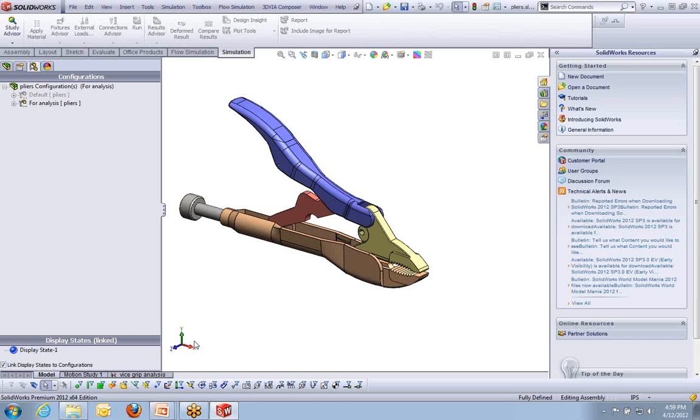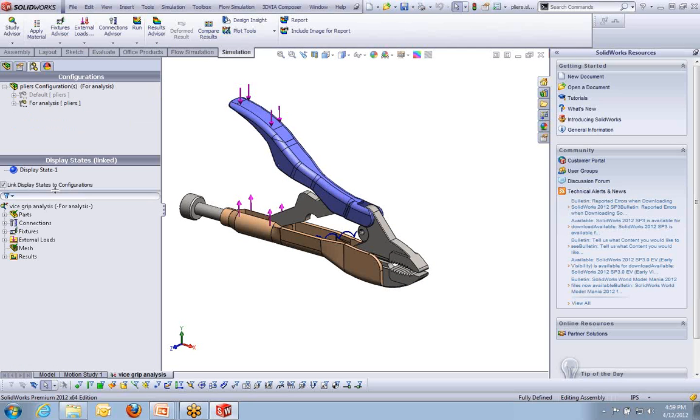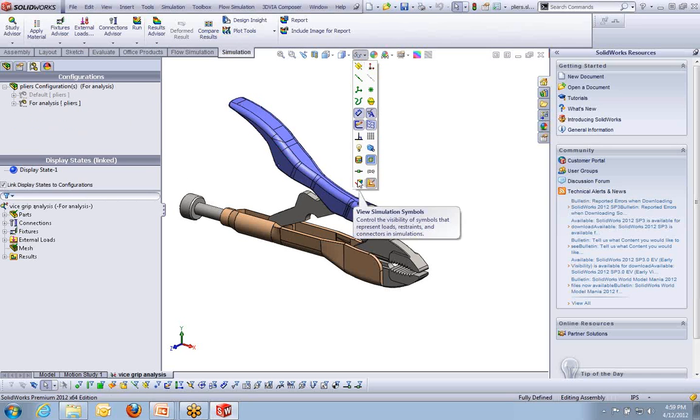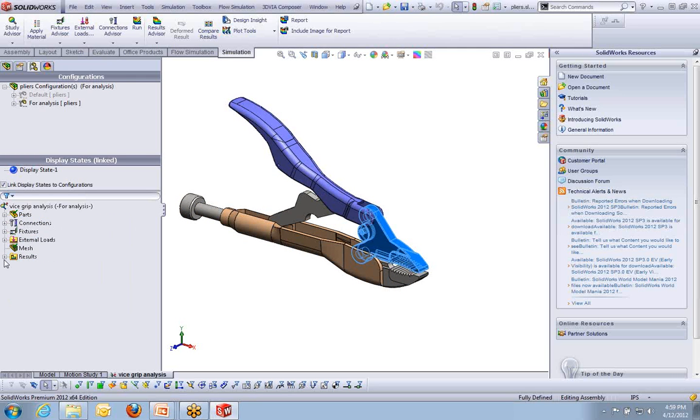Now, before this session, I created the study and ran it. It's here, by script analysis. Again, it has a simulation study tree to track the simulation related features, and it's very similar to the SimulationXpress study tree, but we have differences. We have a parts folder here, since we're analyzing our assembly, and we have a connections folder. Actually three, we have a mesh folder here as well.